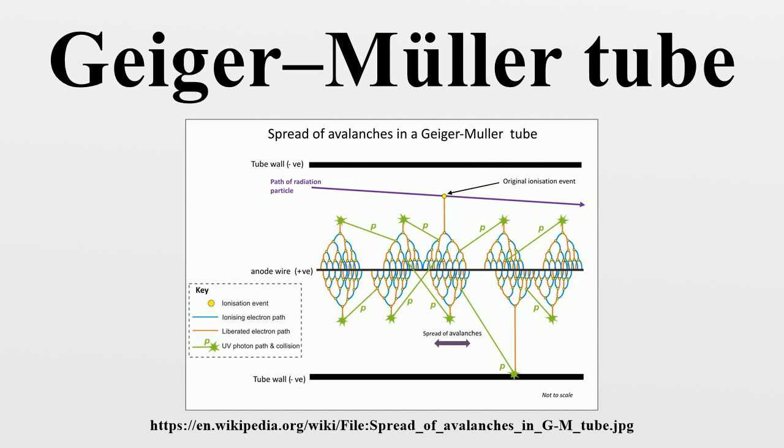The halogen tube discharge mechanism takes advantage of a metastable state of the inert gas atom to more readily ionize a halogen molecule than an organic vapor, enabling the tube to operate at much lower voltages, typically 400 to 600 volts instead of 900–1200 volts. This type of GM tube is therefore by far the most common form now.